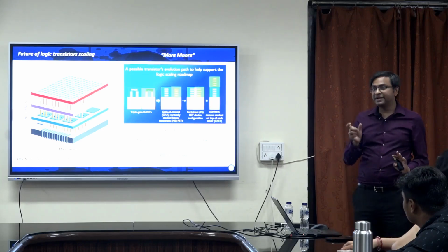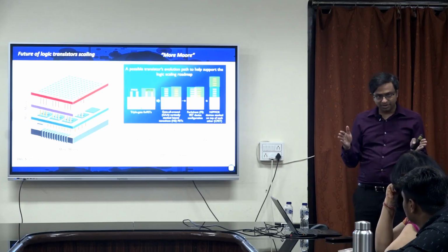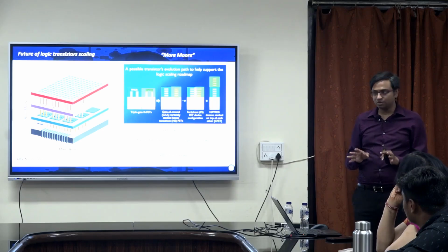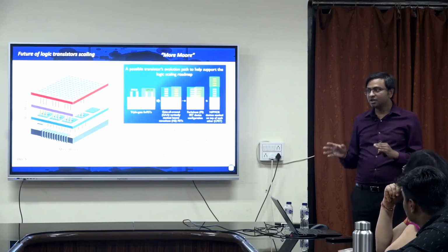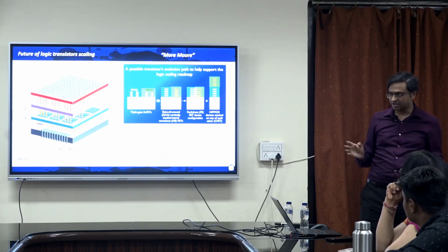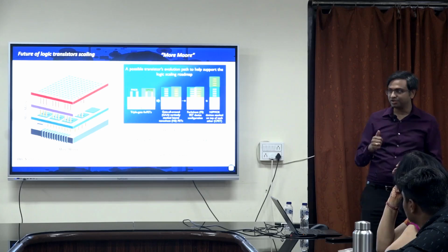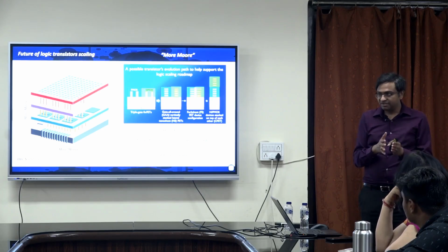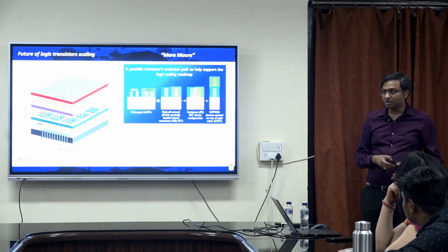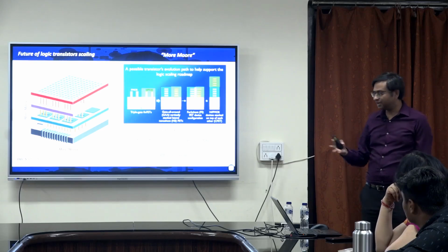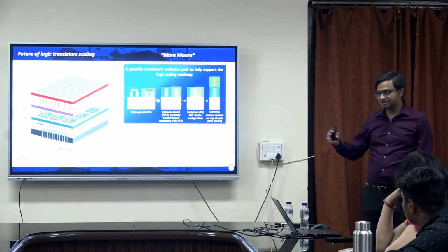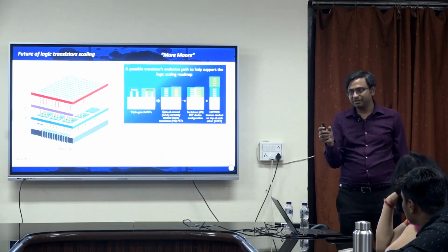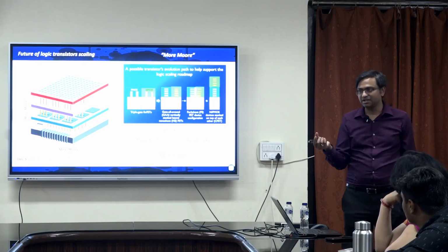So the limitation of why we can't make the channel much shorter has nothing to do with fundamental material properties. It has more to do with lithographic capabilities. The tools made by ASML, a company based in the Netherlands, make the EUV tools. They cannot currently scale down how small a feature we can get using this UV technology. Once that is enabled, these materials are ready to be scaled much further. But then one day we will probably get to a limit where your transistor channel length cannot be made below, let's say, 10 nanometer, right?